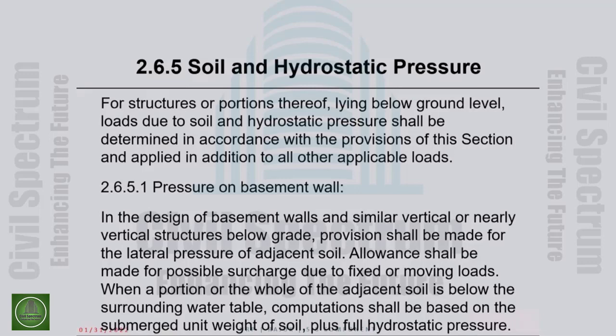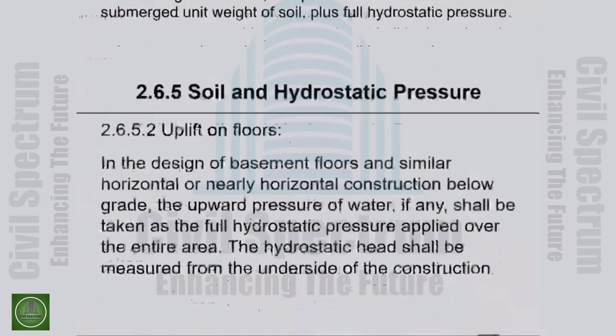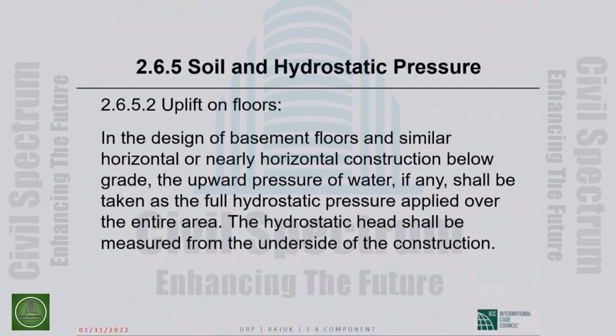Now the water will apply pressure, and if it is sand, the sand will apply pressure. So fully submerged under the water table. Uplift on floors. In the design of basement floors and similar horizontal or nearly horizontal construction below grade, the upward pressure of water, if any, shall be taken as the full hydrostatic pressure applied over the entire area. The hydrostatic head shall be measured from the underside of the construction.